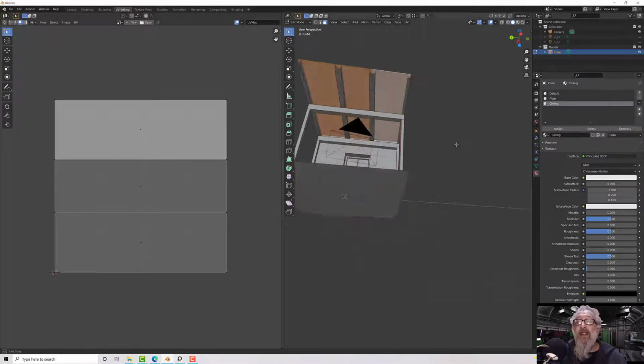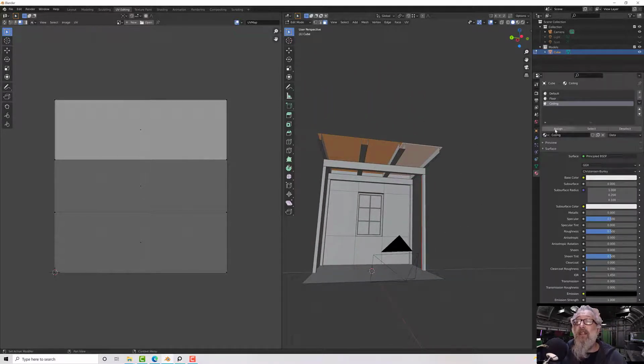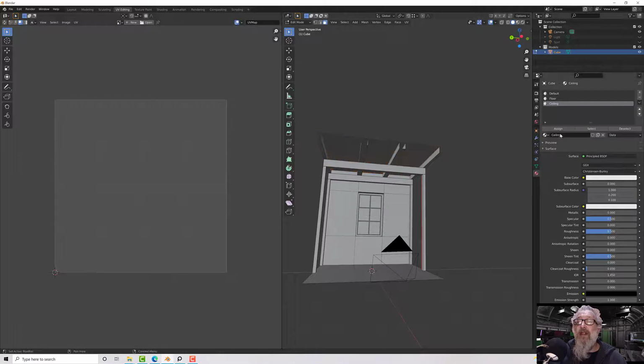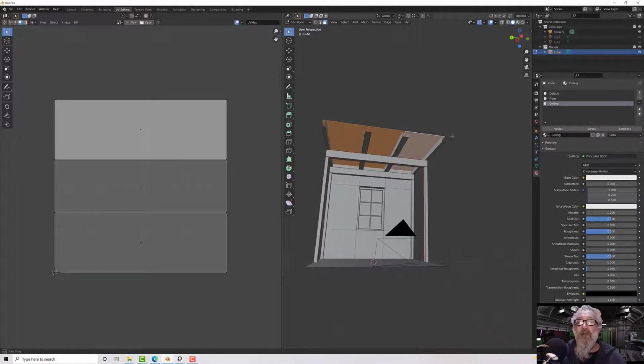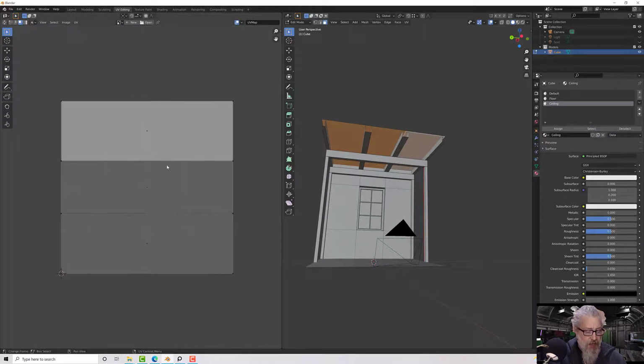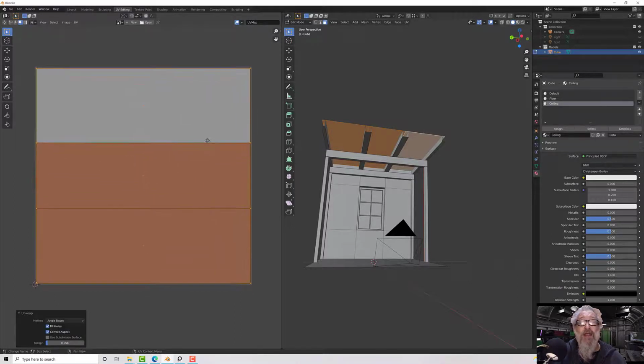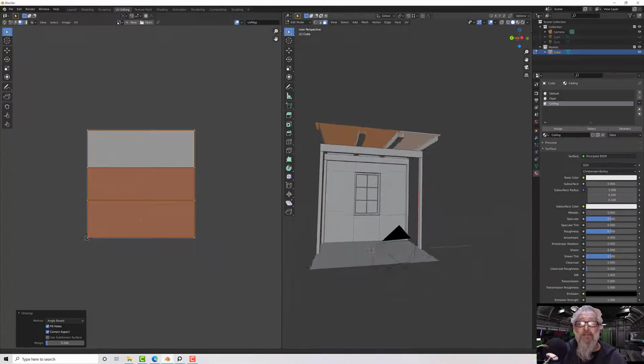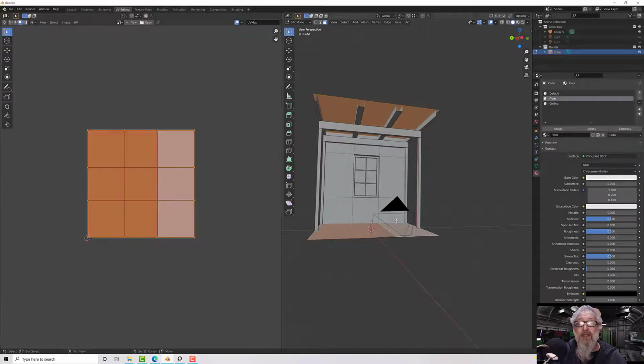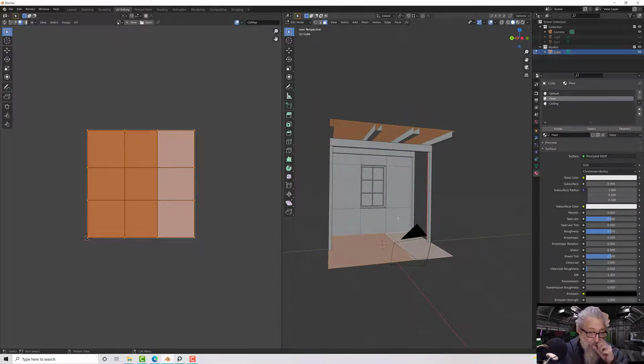And with that selected and our polygon selected, I'll hit assign. I'll click off and just hit select to make sure it worked. In the UV view, I'll hit A to make sure everything's selected, and then U and unwrap. There we go. And quite often when I'm doing this, I'll hide things as I go so that I can see what I've got left to UV.